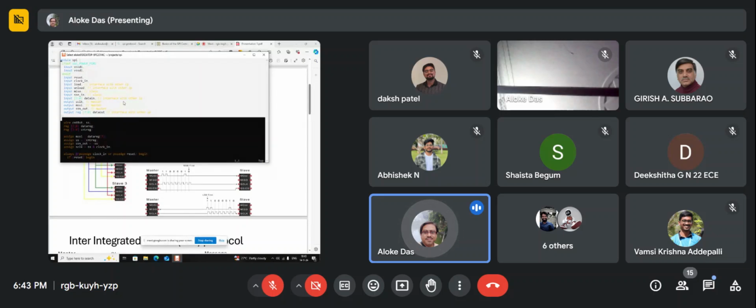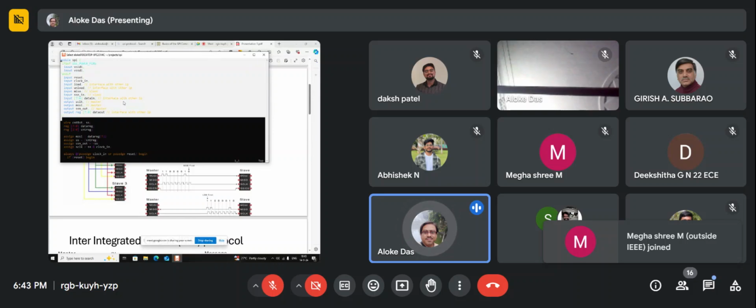MPEG decoder is another hardware present in the camera. When you hook up the MPEG chip with your SPI protocol, you start to experience what the problems are, what more signals are needed, how it can be coded, how it can be worked. Again, when you capture a picture, your MPEG has encoded it and given it back to the SPI protocol.